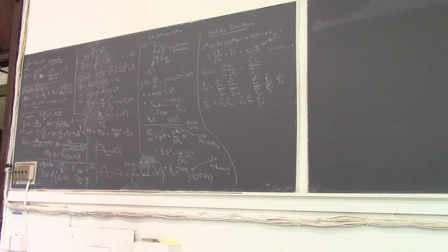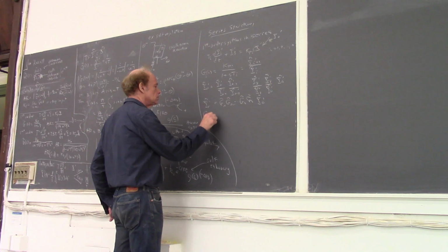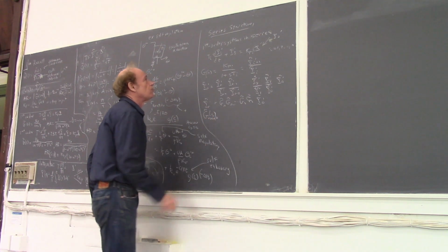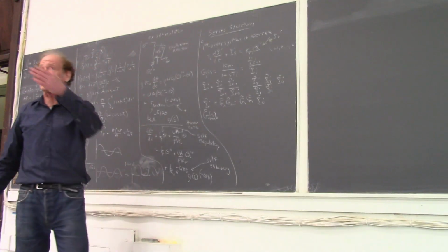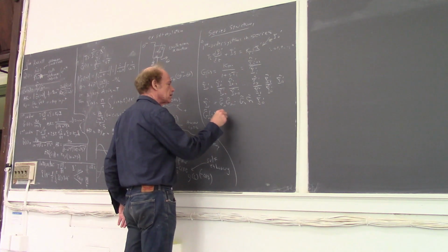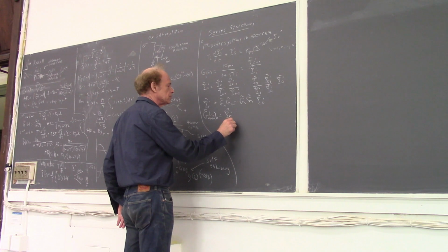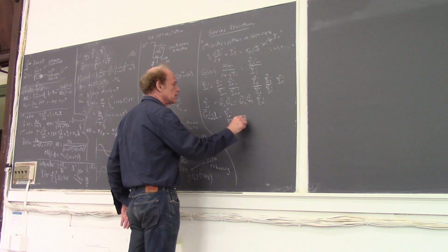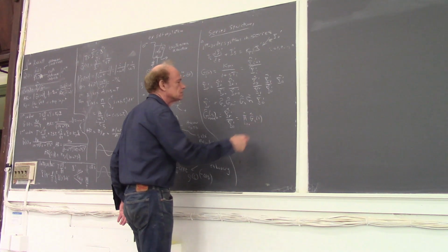In other words, the overall g for n first-order systems in series, which you can think of as n CSTRs in series, is the product, which is equal to yn prime tilde over y0 prime tilde. It's just the product for i equals 1 to n of gi tilde of s.